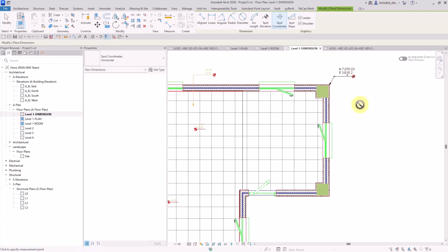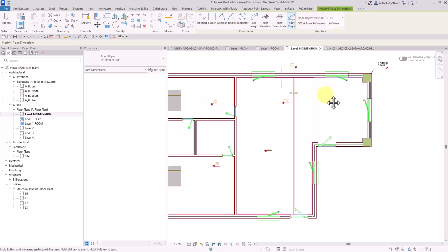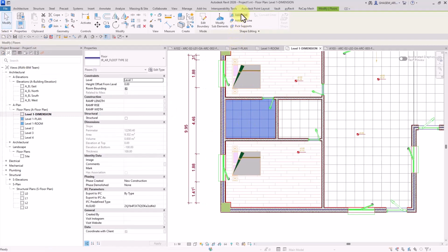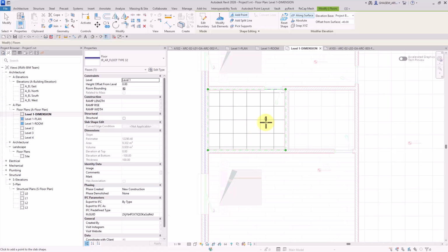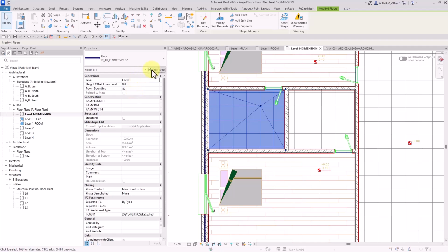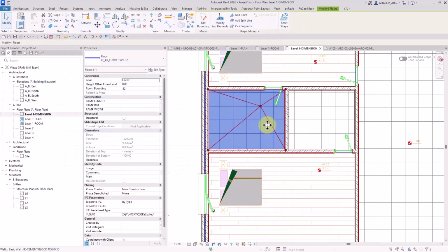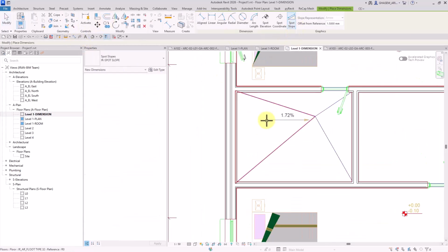And then, lastly, we can control and manage our slopes using spot slopes. And again, its sub-items are set in the ribbon. For example, I'm going to select this, add points, give me -40. And then I'm going to select this point. Now open up type properties, then enter edit assembly. As I said, we can set these outside the core. And also I'm going to activate variable. Alright, now I can specify my slope through this item. For example, like this.